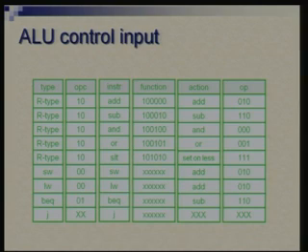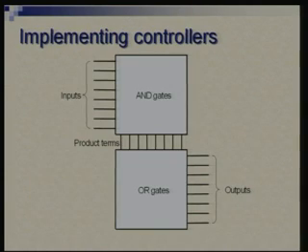So, the PLA stands for programmable logic array. Logic array means that you have an array of gates, and this structure is somewhat universal. You can program it to implement any desired function. So, the PLA which will implement this would be fairly large. I will not describe the PLA which will implement this, but I will try to illustrate the basic principle. What is the basic idea behind this approach for design?